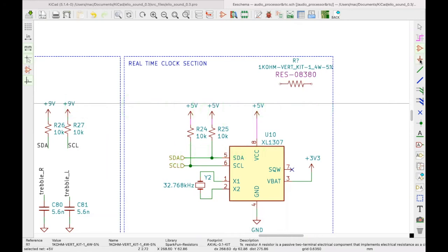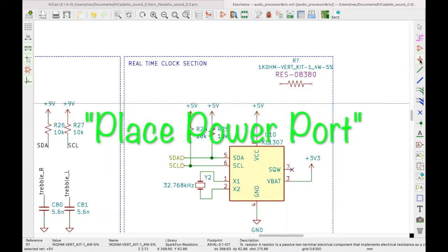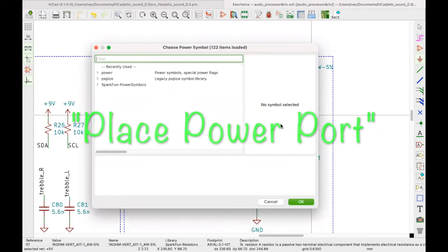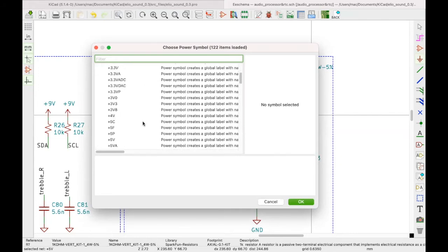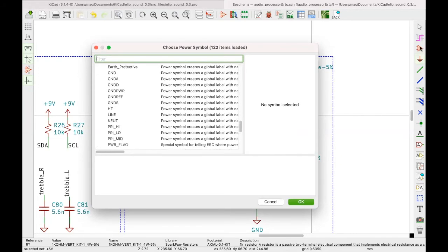So this is the power plane. These are power ports. If you click this, you can now place and come and hit here. It will give you all the powers that are available. Say you need to check on power, say we are talking about ground, 5V, 3.3 volts, VCC, VDD, ground reference, ADC. All these here, you can be using this tool.